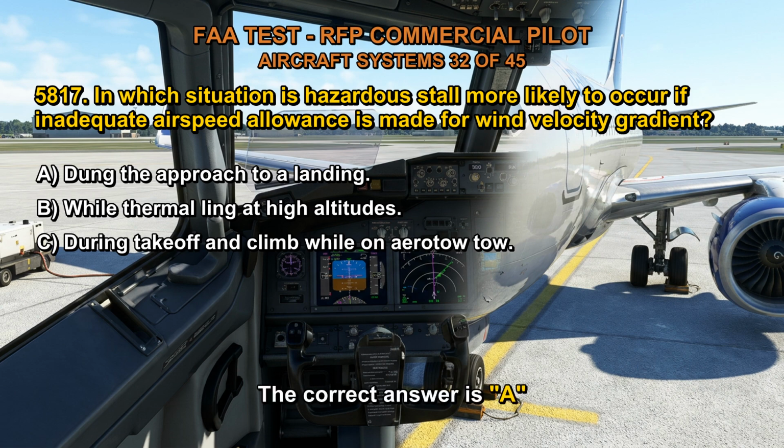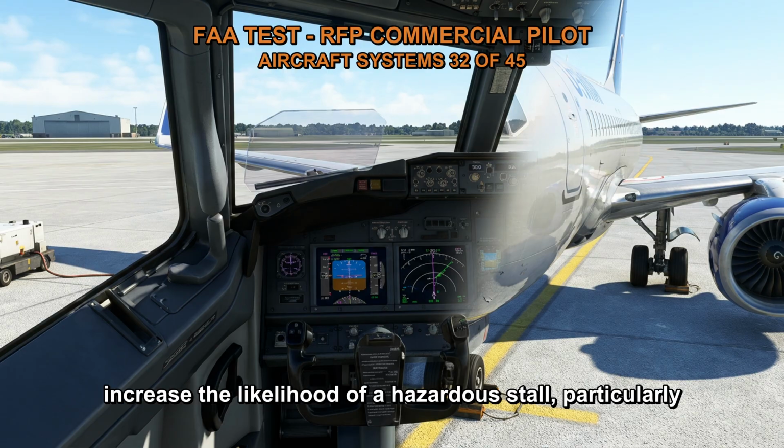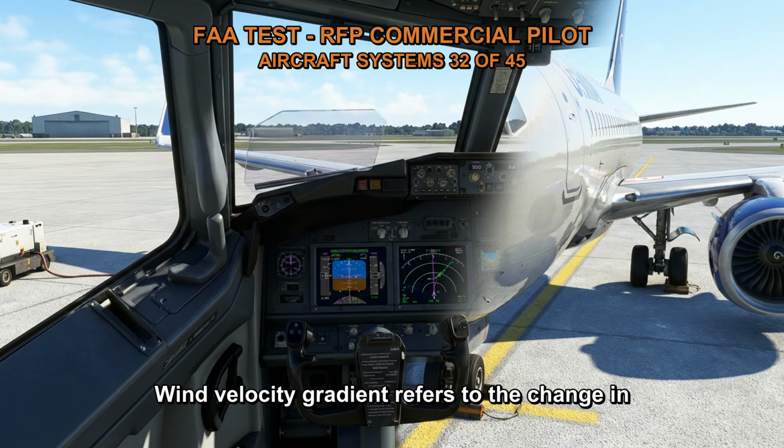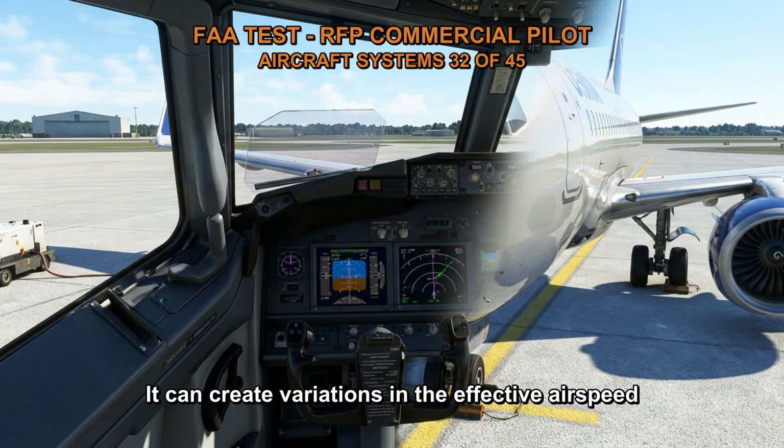The correct answer is A. Inadequate airspeed allowance for wind velocity gradient can increase the likelihood of a hazardous stall, particularly during the approach to a landing. Wind velocity gradient refers to the change in wind speed with altitude. It can create variations in the effective airspeed experienced by the aircraft at different altitudes.